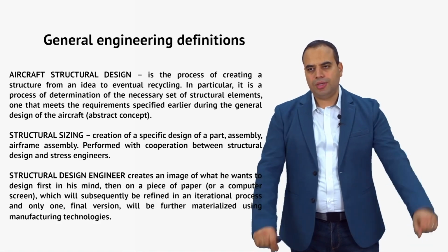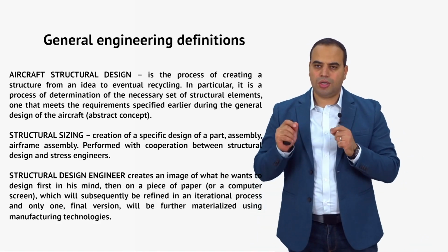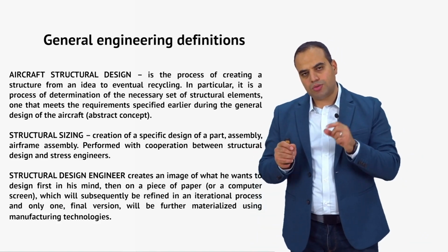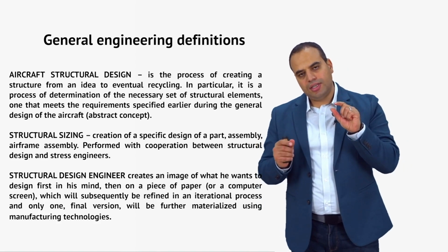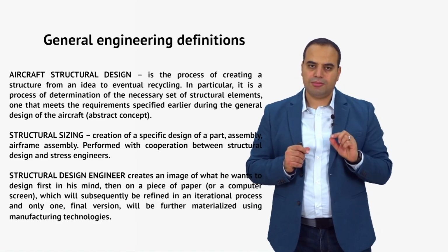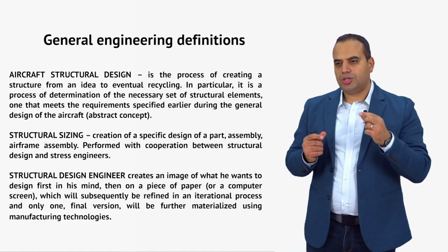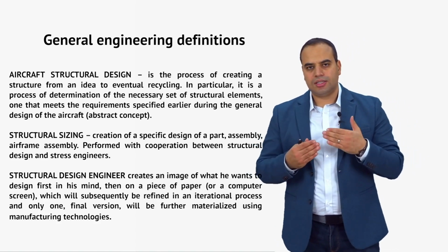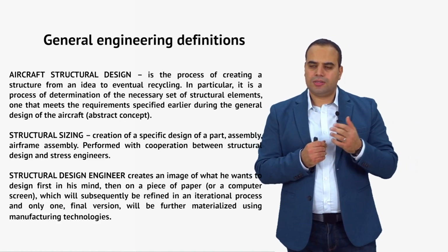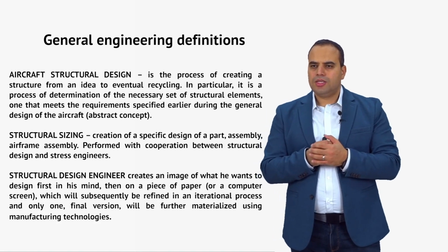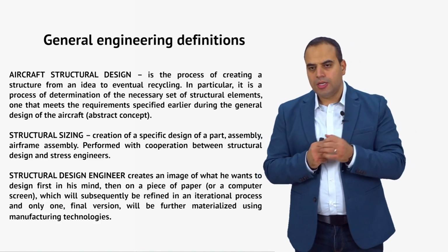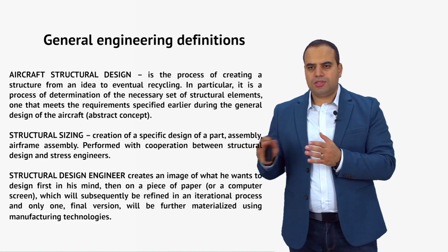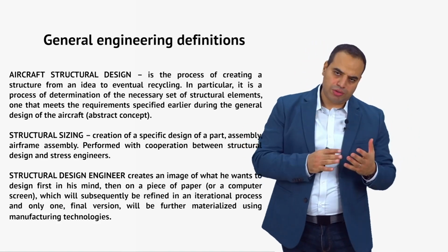When we know the structural elements that are going to be included, after that we have to size them. We have to define how thick every structural element is going to be, how much loading it is going to take, and its strength margins, right? So this process is done by both stress engineers and design engineers.